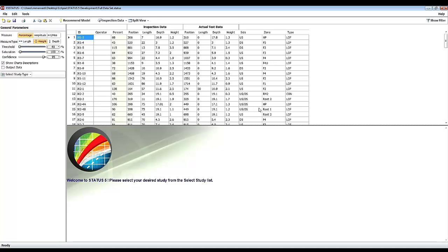To do that, when they do that inspection, our software is going to be used so that they can input their findings into our software, and our software can do calculations to demonstrate the capability of the technique based on probability of detection curves, which show the chance or probability of detecting a specific size of defect with that technique.